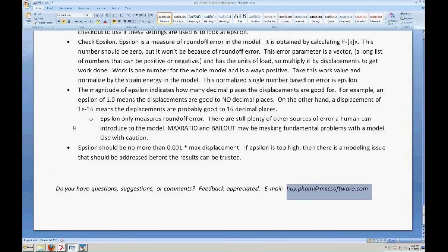We've got a couple questions. I'm going to try to cover them as best I can. Adrian Niegu has a question: what if you select none instead of property or averaging? Adrian, that is an excellent point. If you select none, you won't average anything with anything. I think that actually gives you the best answer, because when you average, you take the highest stress and average it with something else, which means you get lower stresses. The problem is that managers like smooth color plots. Some managers think if your stress plot doesn't look smooth, it isn't very good. So I actually do a little bit of averaging just to keep everybody happy. If I had a choice, I would actually set the averaging to none.